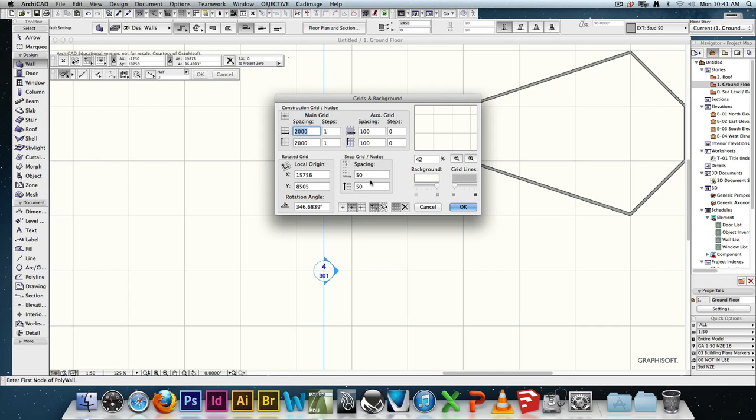So maybe the idea of just being able to sketch something up is really important to you. You don't want to have to go, right, this is going to be 3.5 meters by 2 meters. So you could turn the snap grid on, and that means that when you go and draw something, it's going to be snapping to 50 mil increments. So when you go and dimension it up, it doesn't look ugly. It's nice 50 mil increments. It's actually buildable. Okay? Or at least it's snapping to a 50 mil grid. It doesn't always work out nicely, but cool. Some things are just impossible.